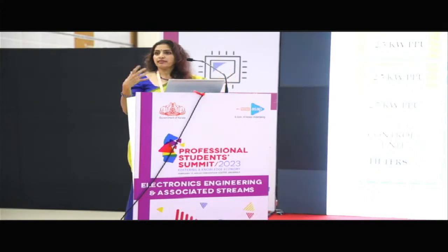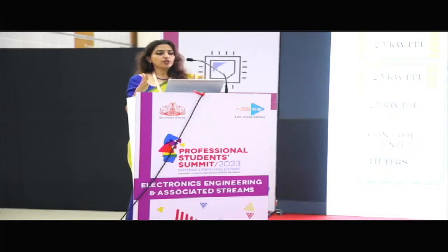Normally what we do in our ground systems, we work with resistive load, capacitive load or inductive load, but plasma is a total animal altogether. It is a complex load, so it has certain oscillation which can affect the electronics. So there are certain filters at the output, and at the input also we have filters to protect it from EMI and EMC, and the design of all this is very, very critical for the working of that package.